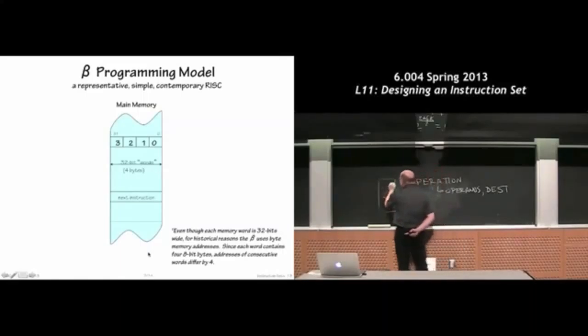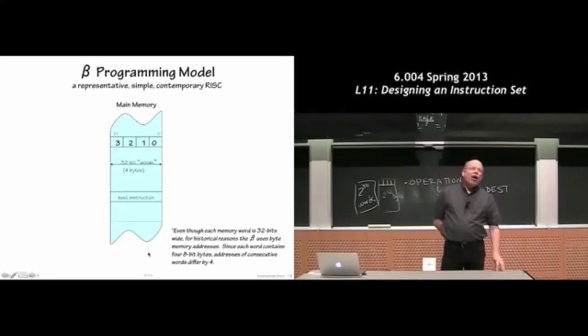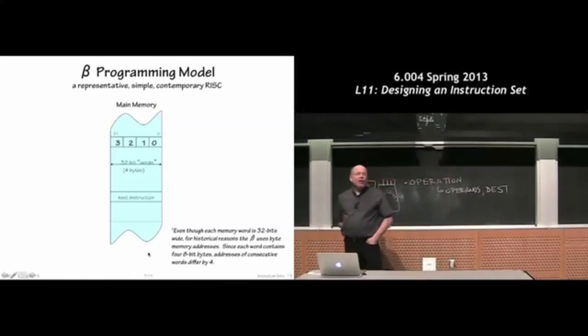We're actually going to organize the memory as words. So we're going to have a memory that's actually 2 to the 30th words. And each word has 4 bytes of information in it. And although most modern computers have a way of actually reading and writing a single byte from memory, our machine is going to be pretty dumb. It is just going to read and write 32-bit words. It's not going to have any byte-level operations, which might be a deficiency, might not. You can certainly write sequences of 32-bit operations that let you pick up a whole word and shift it and mask it to get just the byte you want. And that might turn out to be a good thing. We'll see how it evolves here.